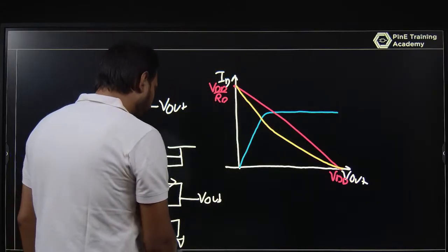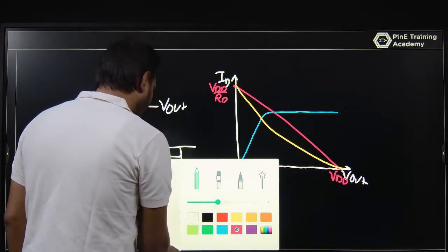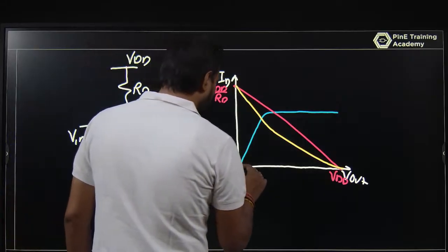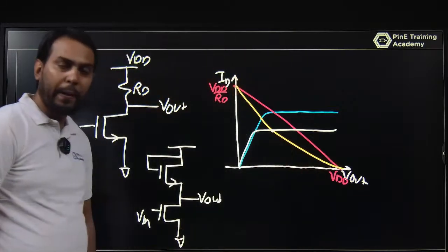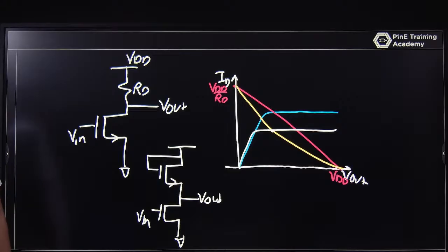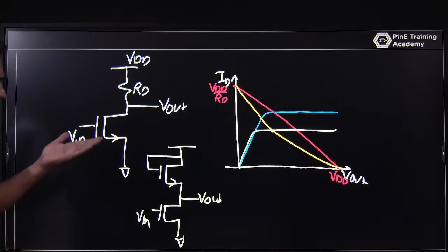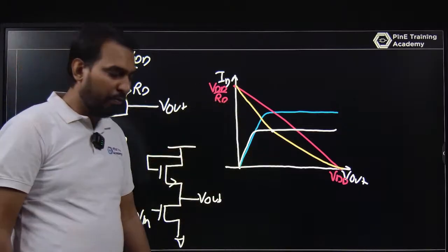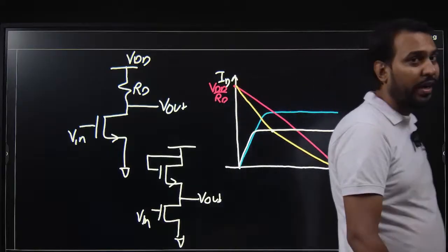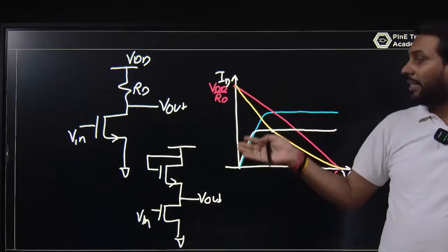So you can put a lower VGS. At lower VGS the MOSFET is maintained like this. So you are using a lower gate voltage, and only then will you find that the MOSFET is maintained in the saturation region. If you go for a higher Vx, a higher gate voltage, that MOSFET may enter the linear region. This will not provide that particular resistance like the load line shown here for 1 by gm.